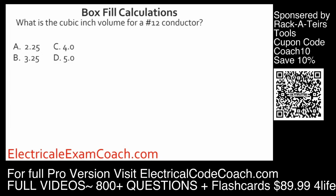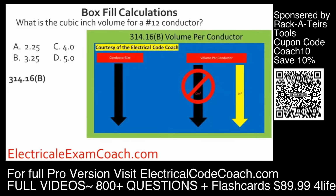What is the cubic inch volume for a number 12 conductor? Head back to 314.16(B), start on the left-hand side and find our size conductor, then cross over to the cubic inch volume. And it's stating that for every number 12 that's in that box, according to the count, which we're getting ready to learn, takes up 2.25 cubic inches of that box.